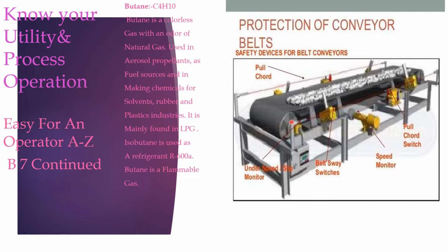Normally, people used to clean the belt during running, and the sticky material or any solid material dust particles get stuck up with the belt conveyor, which will affect the belt moving in correct position and cause sway. So, they will clean it online. That is to be avoided.